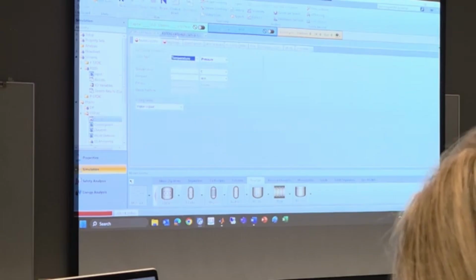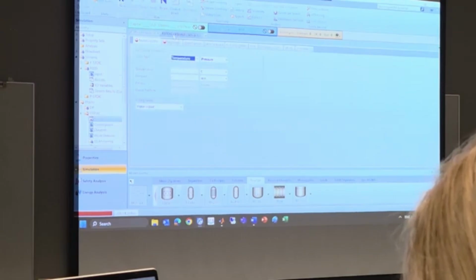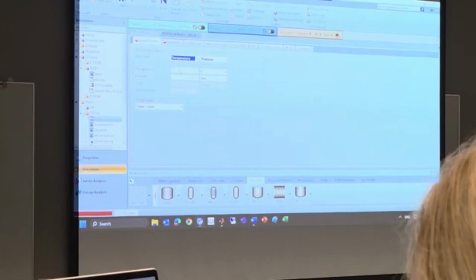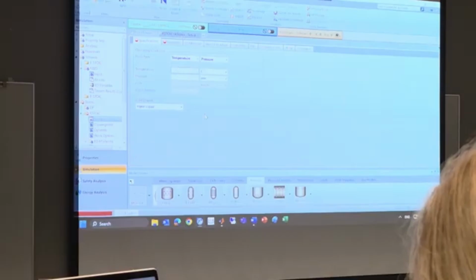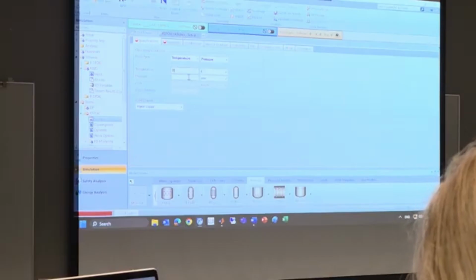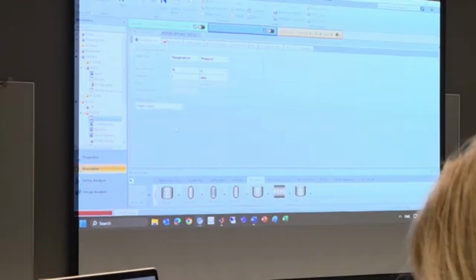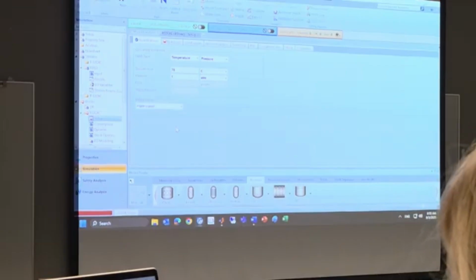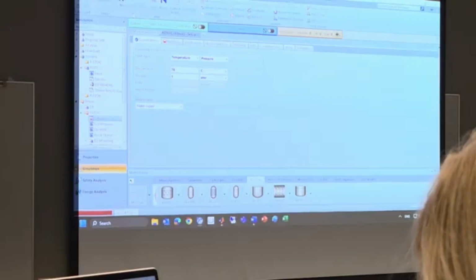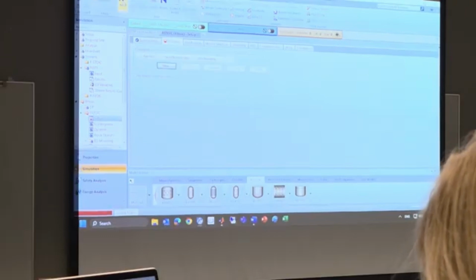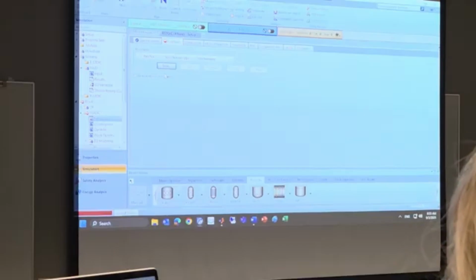Now we are working on the stoichiometric based reactor, RStoic. What is required? Temperature and pressure are required. And please make sure to check the valid phases. If you go to valid phases, the default is vapor-liquid. Okay, I have this vapor-liquid phase. And if you go next, you are working on reactions. You will pay attention to it. We are working on reactions.